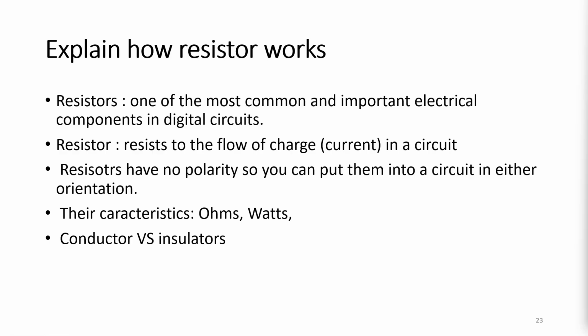Now, let's talk about another component, a resistor. Resistors are one of the most common and important electrical components in digital circuits. A resistor, as its name indicates, resists the flow of charge or current in a circuit. Resistors have no polarity, so you can put them into a circuit in either orientation. Resistors have two characteristics, ohms and watts.